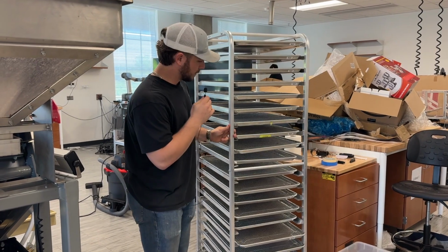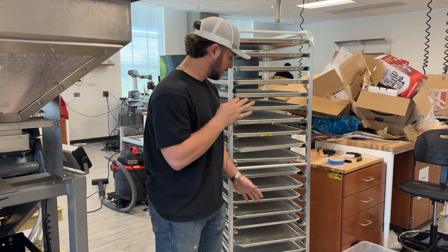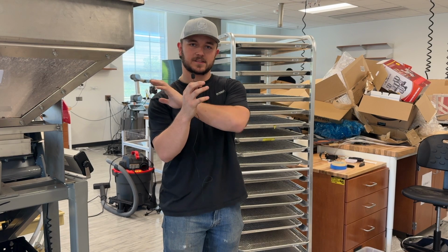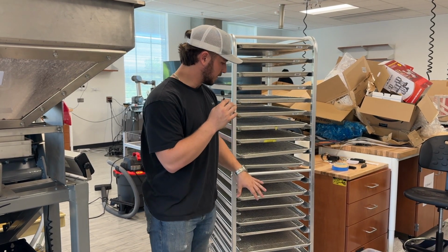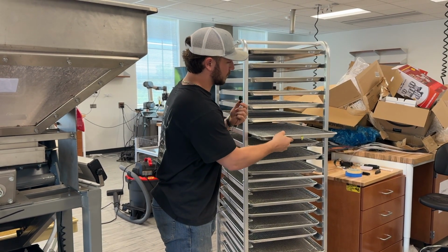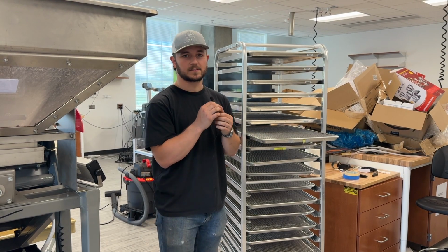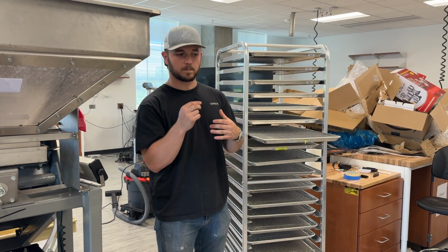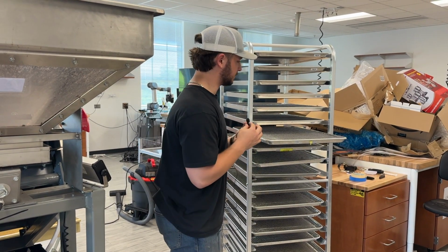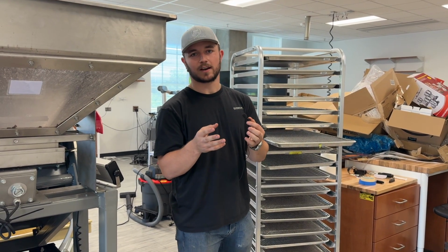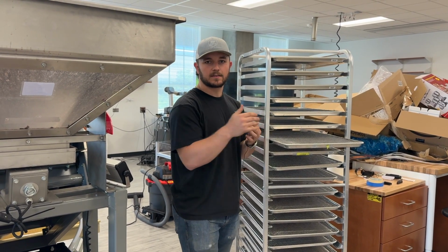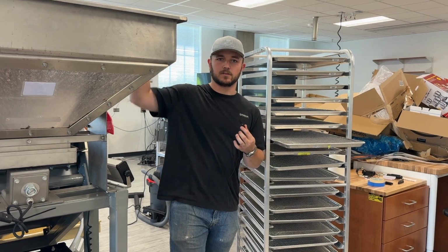From conditioning, we've been playing with air drying time because of how we've seen pecan shell surface dynamics change things within the cracking process. This is an independent variable that we've recently introduced. We have trays here with little grates in them. This isn't something that is standard in industry. There is a certain amount of time that they spend on conveyors, but they don't purposely let the pecans sit and dry for some time. There are some food regulation aspects that limit how long you can let them sit for. We're just seeing how far we can push that to maybe increase half yield later on.